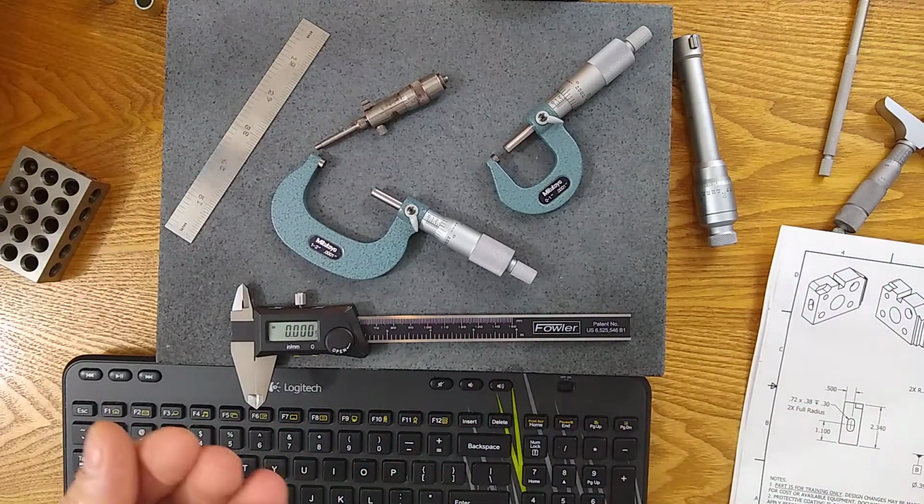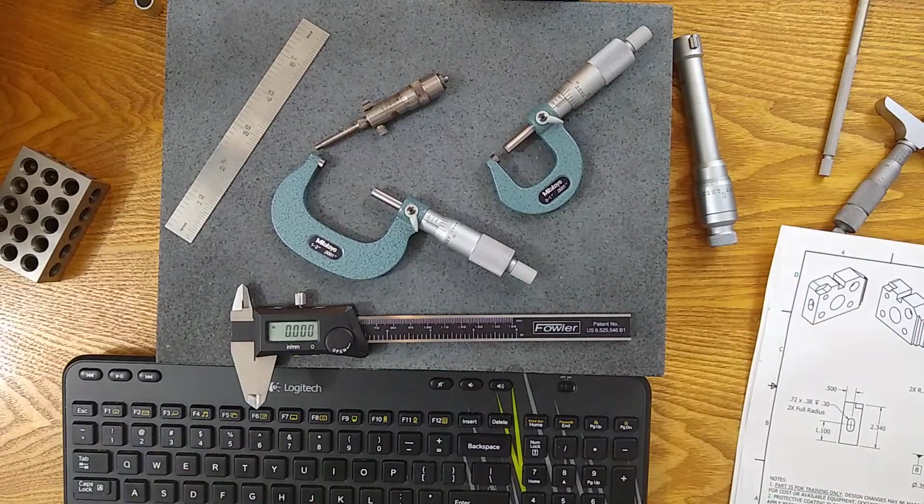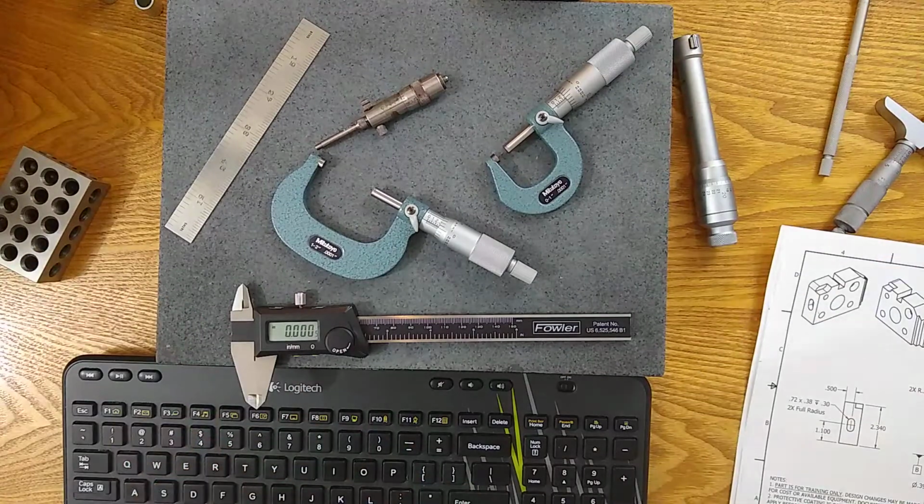So first of all, I've said it many times, and I want to hammer this home: always compare the tolerance zone to the gauge accuracy. So know what your gauge accuracy is, know what your tolerance zone is. Do that uncertainty ratio, 10-to-1 rule of thumb. Do that, figure that out. You use the gauges enough, you'll know right away. And then you just check with the print.